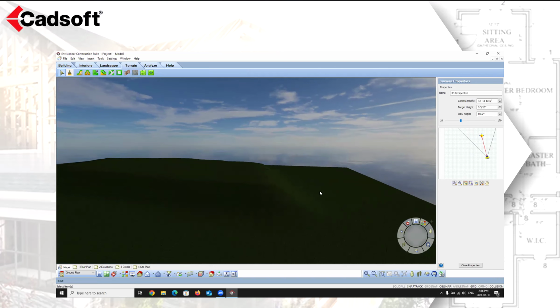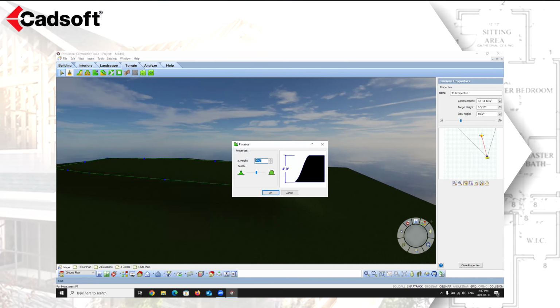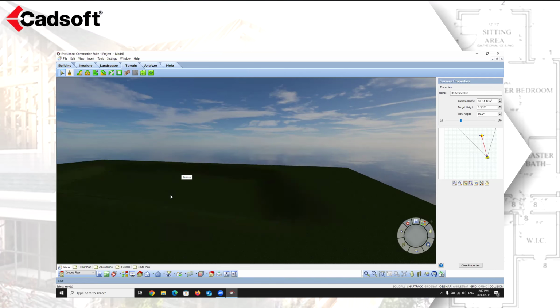surface. And again, if you wanted to, you could use this plateau in a negative value. So if I went back in and I said -4 feet, we are now creating a depression, which I could use as a pond if I wanted to. And I could add in some fake water in here, or I can add in a surface to show the water. So it's creating like a pond in my design. So you can use those berms and trenches, slopes and hills and valleys, berms and trenches and plateaus to create any kind of adjustments to the terrain above or below the surface itself.